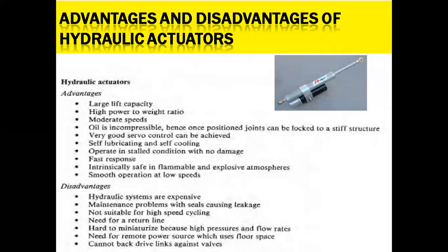Smooth operation is possible without any noise creation, and better accuracy is maintained. Coming to the disadvantages, they are very expensive. There are maintenance problems with seals causing small leakages of pressurized fluid, which leads to a decrease in efficiency. It is not suitable for high speed cycling, and it is hard to miniaturize because high pressure and flow rates are involved.